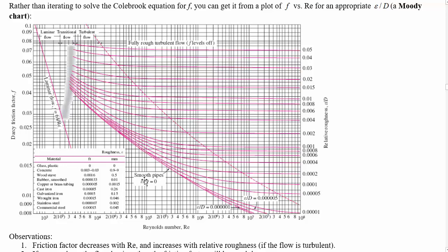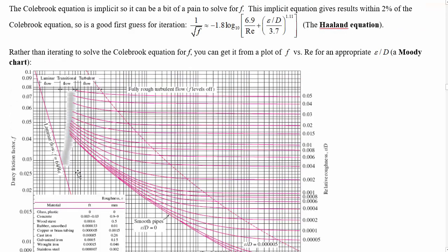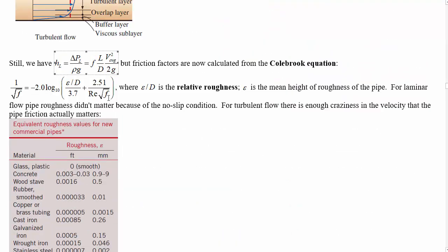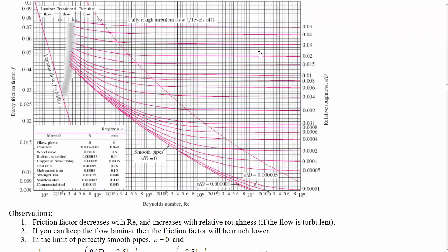So, all right, let's suppose you can do that. If you increase the Reynolds number, then for a given pipe, increasing the Reynolds number means you're increasing the velocity, and you'll find that even though the friction factor is going down, the head loss is going up, because head loss goes like friction factor multiplied by velocity squared. So if friction factor is going like 1 over velocity, then multiplying that by velocity squared, the head loss still increases with velocity, but not to the same extent that it does in fully turbulent flow.